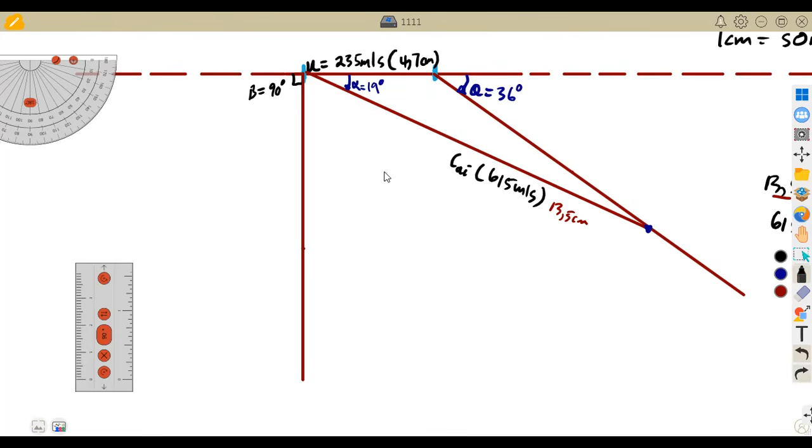So you do not just join to say, okay, I'm just going to join to this point here, or I'm just going to join here. You are supposed to know the length from this point up to this point, or maybe to have an angle. If you are given an angle, you measure that angle where it reaches the line. That is where you're going to have it. But in this case, we are not given the angle at the outlet of the blade.